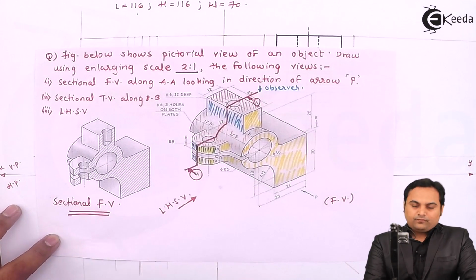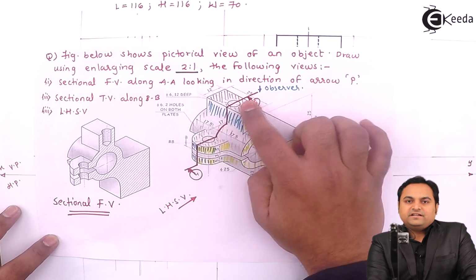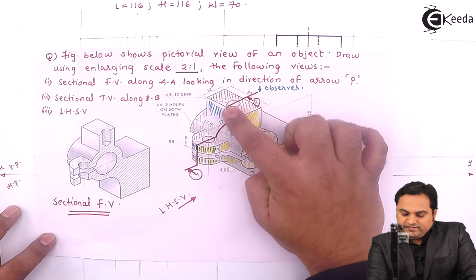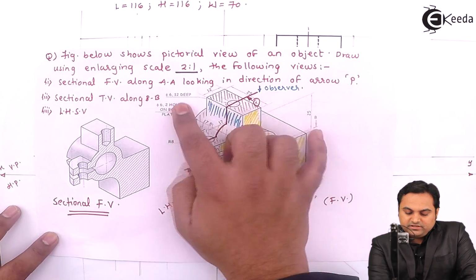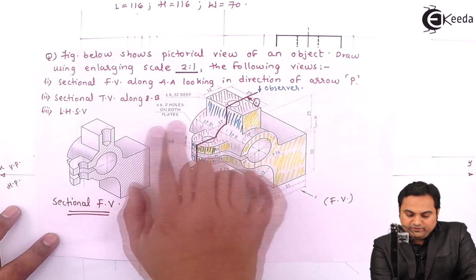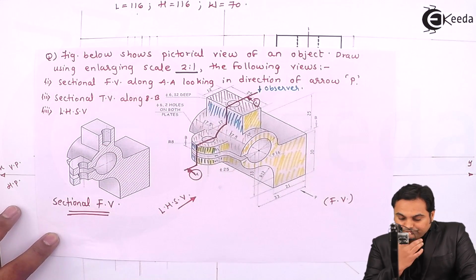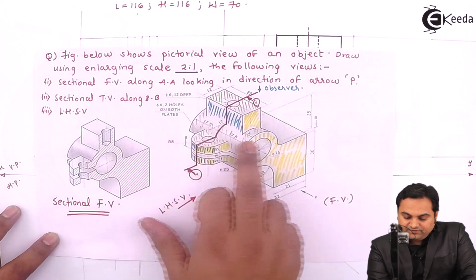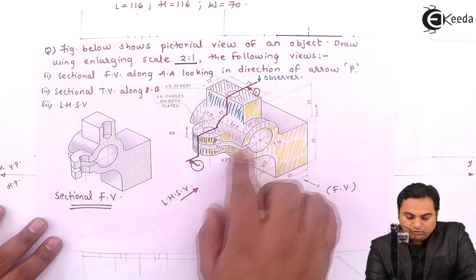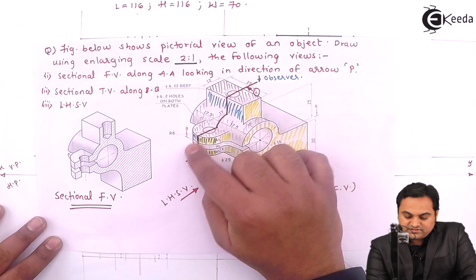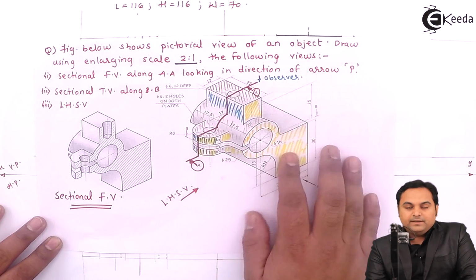So here I can say that first this rectangle is being cut, and inside that there is a circular hole which is 12 mm deep. So when it gets cut, it will look like this, because that is a drilled hole. Then the rectangular surface and this cylindrical surface both will coincide, because all the surfaces are going to be there onto the same plane.